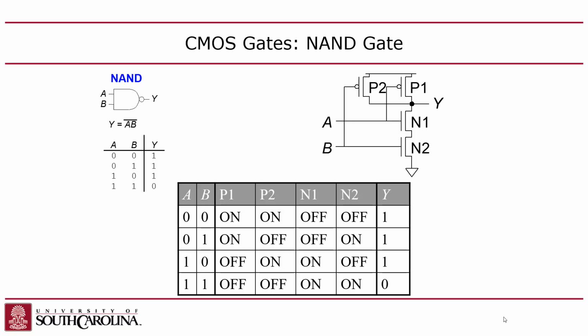This is the part that I think is cool. If you add another input, so I have two inputs, A and B, then for each input I have to have one transistor in the pull-up network and one transistor in the pull-down network. So if I have N inputs, I have 2N transistors, right? But in this case, notice, just like the inverter, A goes to 2 gates, B goes to 2 gates.